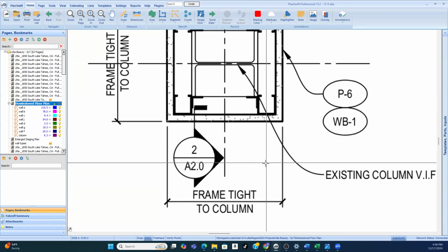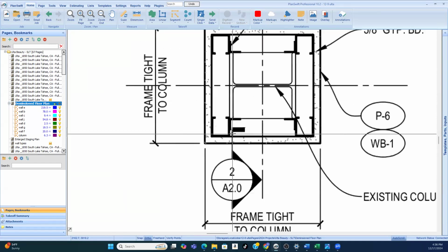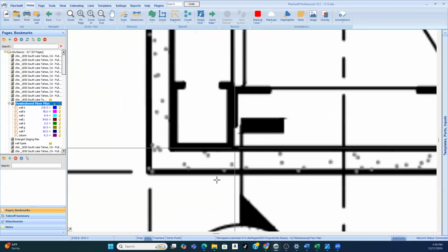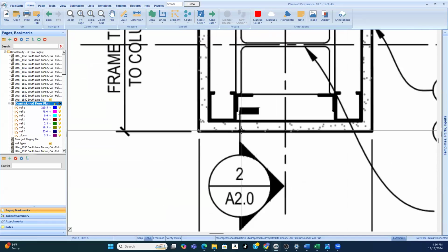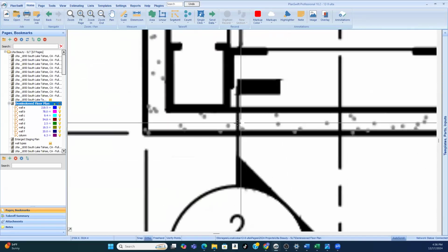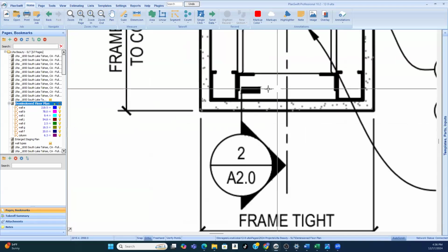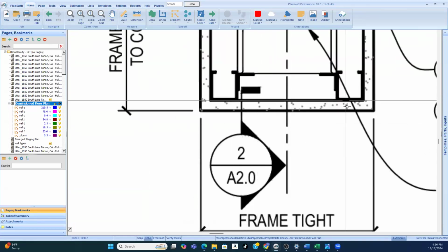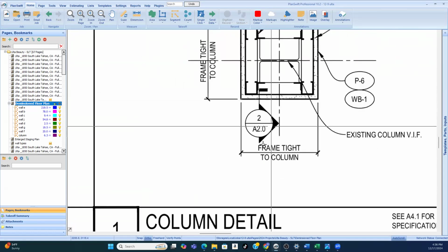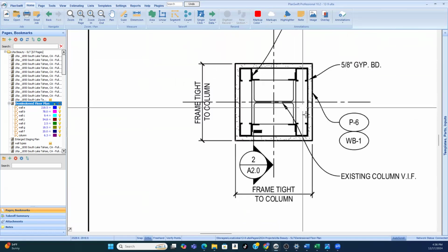It's a section view marker because the leg goes through a section of a wall. The purpose of going through the section is that the leg is like a knife. Pretend the leg is a knife and I'm cutting the wall right there and opening up the wall. I'm standing where I cut and facing in the direction the foot is pointing, so I'm facing to the right.